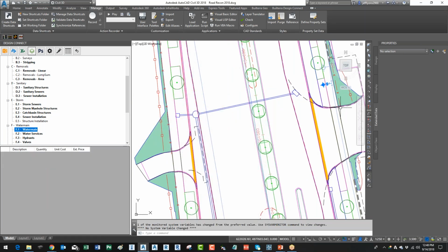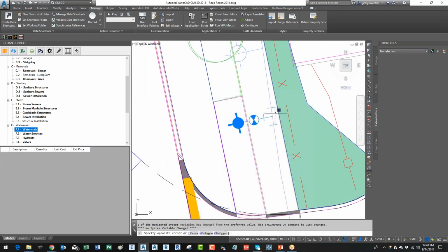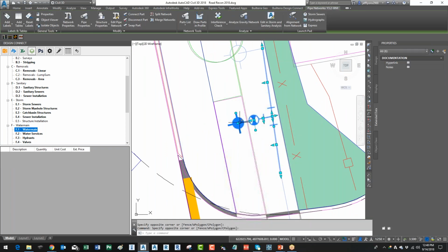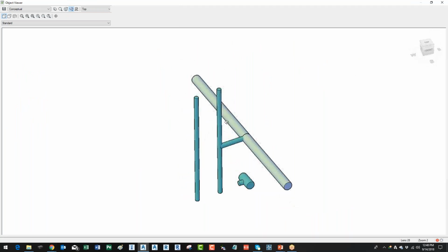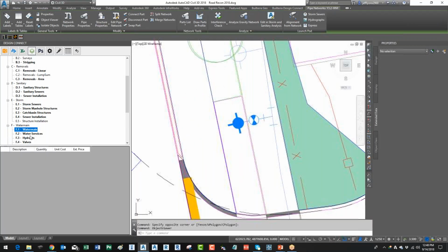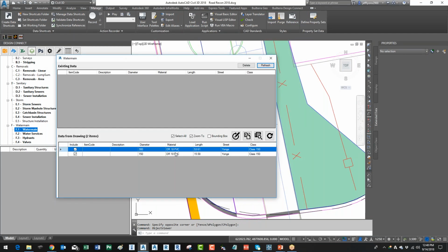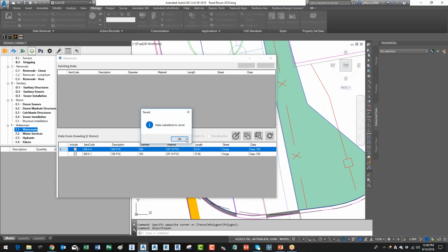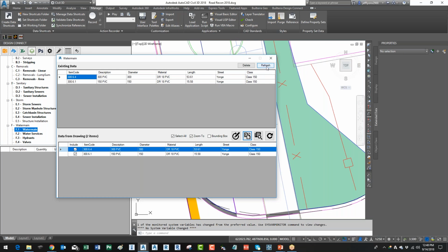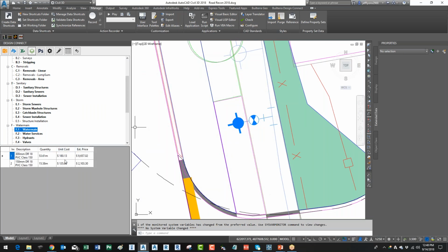Water main, you're going to go through all of these water mains. This was all done using Civil 3D. You can use polylines with property sets if you want, but this is all done with Civil 3D. So if you said water main, it's going to query for the right style on the right layer and sort it by diameter. So we do a reverse lookup and submit. It's always important to do that lookup so then you get the right item codes. And bring it down, and there's our pricing there.